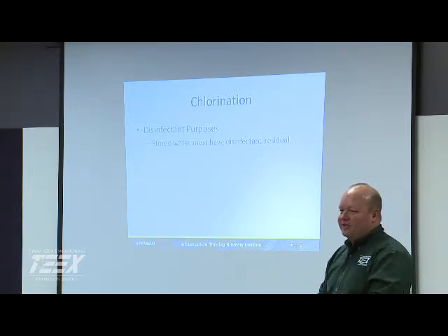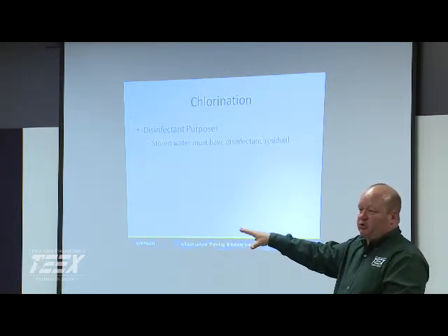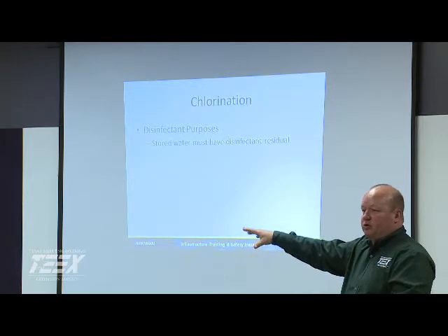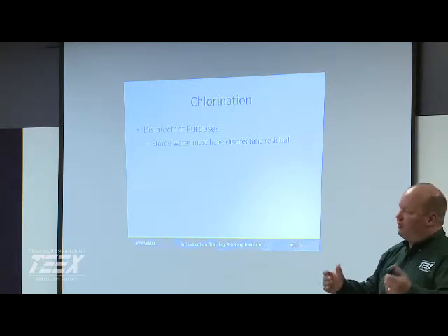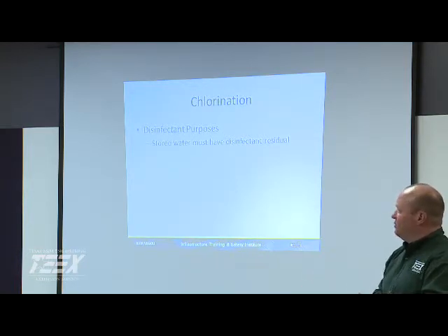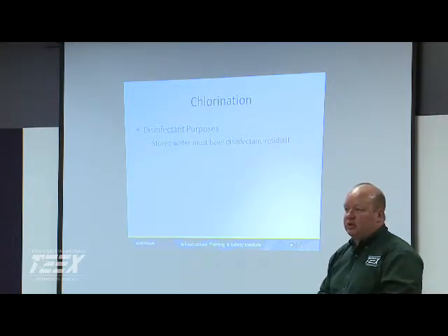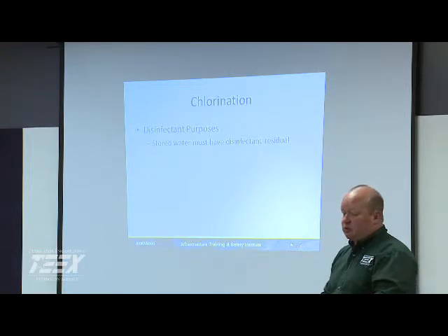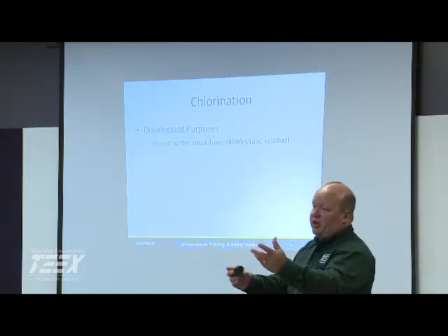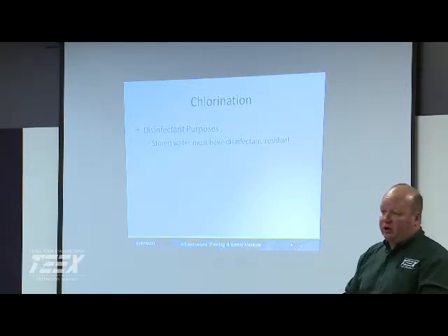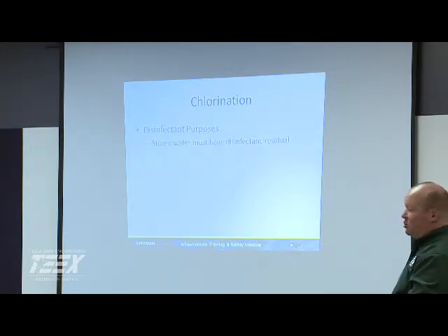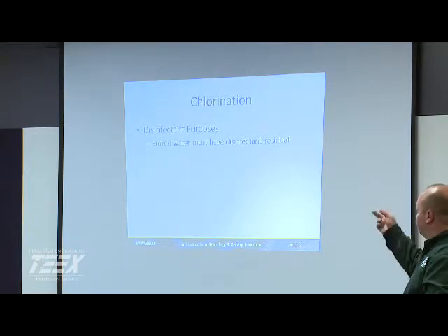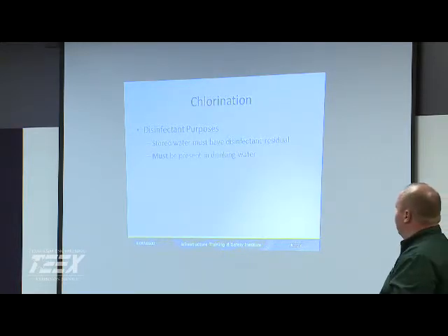Like I said, I'm not a fan of gas, I'm sorry. On the wastewater side, they actually were using liquid. They had evaporators. They were treating 90, 110 MGD a day. And of course, on the wastewater side, you still have a huge demand, so they were using a lot of gas. Then you have to dechlorinate it before you go to your outfalls, so they had a lot of SO2 stored also. So we want to make sure we have a residual, want to get rid of that demand.